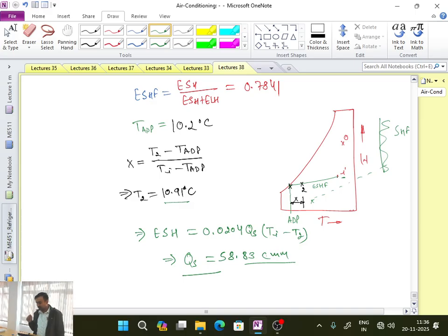Okay, so what will I be doing now, please tell me. The next point is, in order to maintain the room condition, as I told you in that conceptual understanding, if the volumetric flow rate we are taking from the ambient is less, then we will switch on the fan speed, or fully open the dampers.